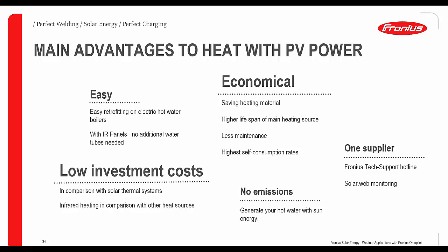Also make sure that there is no active electronic in the heating rod, because of course with our PWM signal or output we would not be able to supply any power for any additional active electronic circuit in the heating rod. So therefore please use just the easy, simple ones. Good. So that was the question so far.